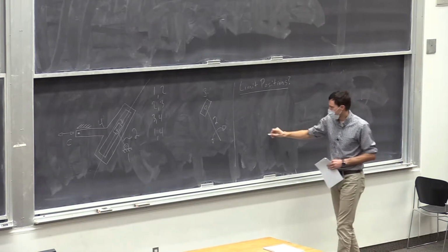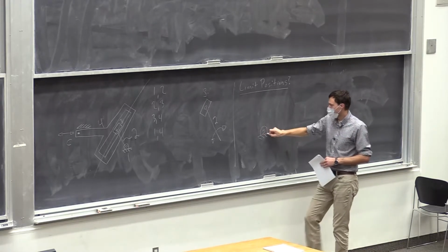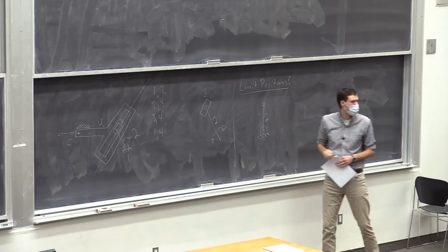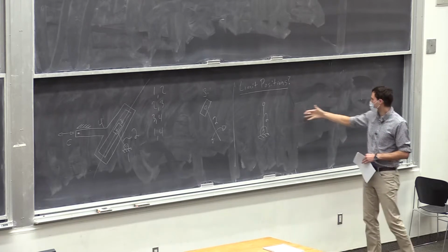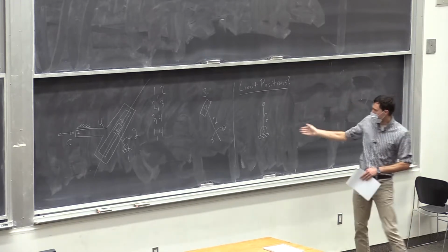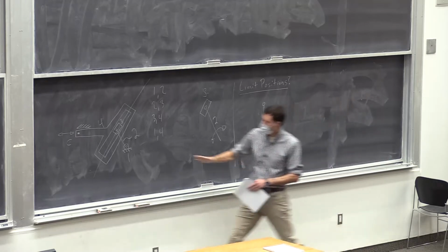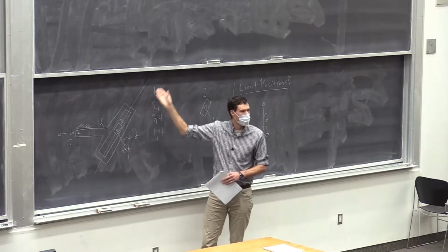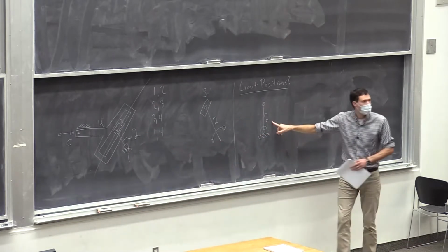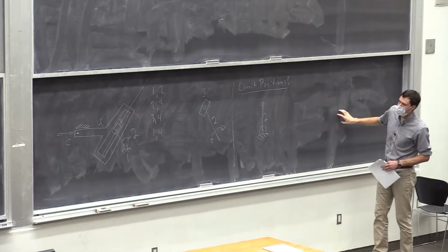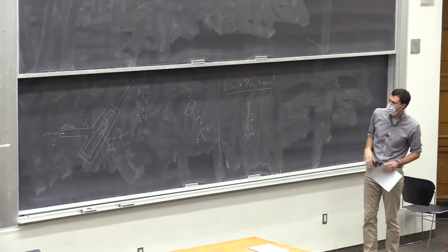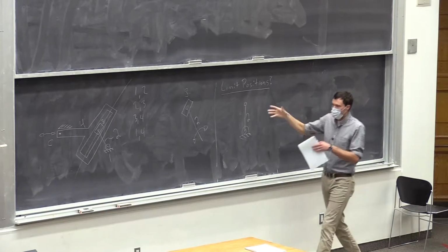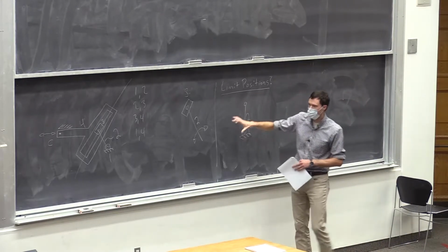So I would suggest you actually sketch out the mechanism and try out some candidate drawings. Here's link 2 in the vertical position. Okay, and I would try vertical, right, down, left. And you could try parallel or perpendicular to this axis, that's like this sliding axis. Just do a quick sketch of each one. It'll take you 2 minutes to sketch out, what is that, 4, 5, 6 or 8 options off to the side. And once you do that, you can try and sketch the whole mechanism on there.